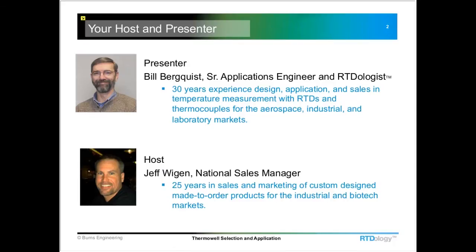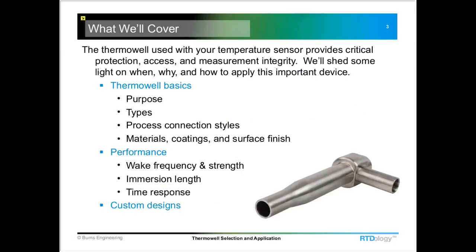Well, good afternoon, everybody. Today what we're going to talk about is how to select a Thermowell, some of the different materials and surface finishes, immersion lengths and their importance, and spend a little bit of time on wake frequency and strength calculations, what I think is one of the more important aspects of selecting a Thermowell.